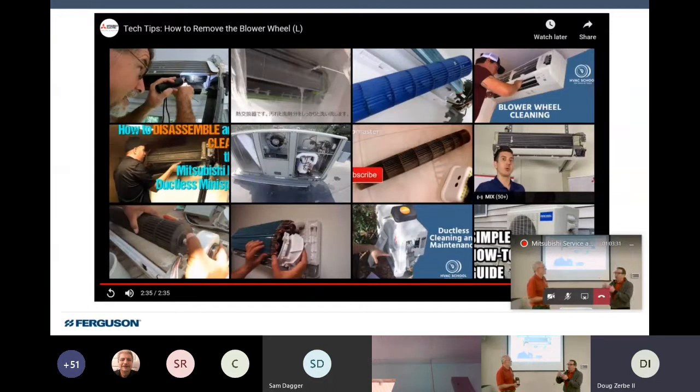That's a good idea, with the electrical strain that could be in there and the polarized plugs. So before he did that, he went through the little hole that goes over the offset. When that drain pan snaps on, there's a little knockout there. He puts the wire through the knockout, grabs another part of the unit and lets that hang. And then it's not in your way either.